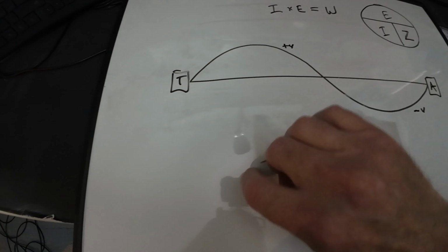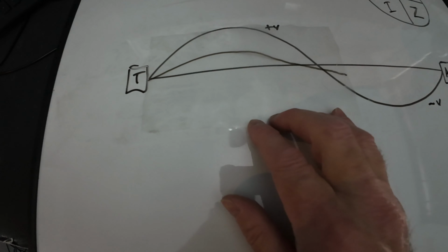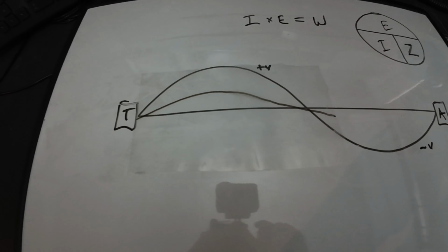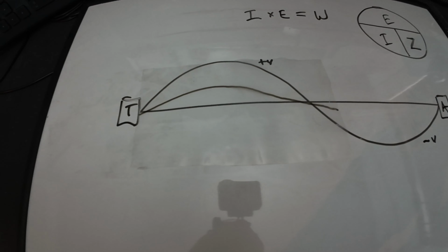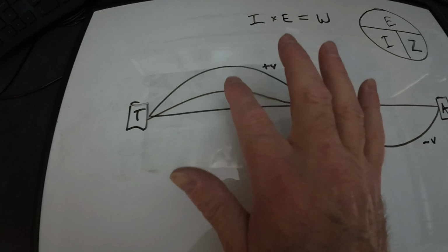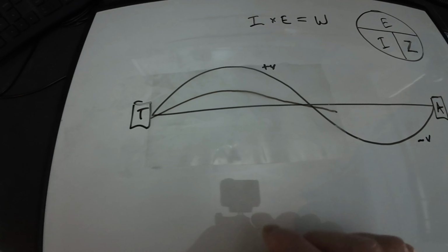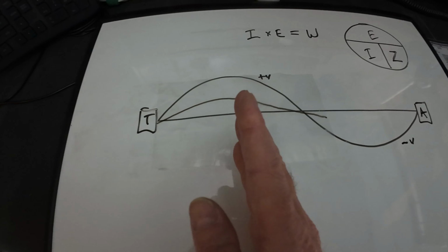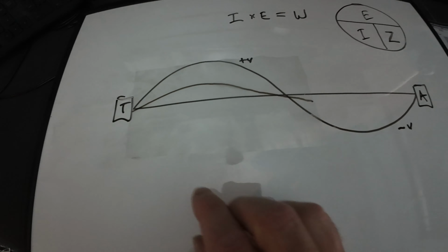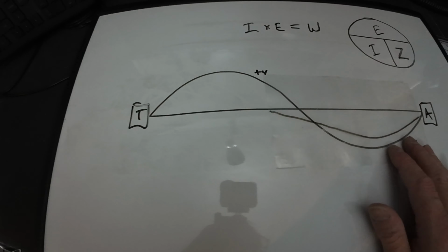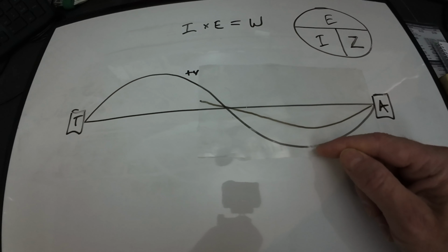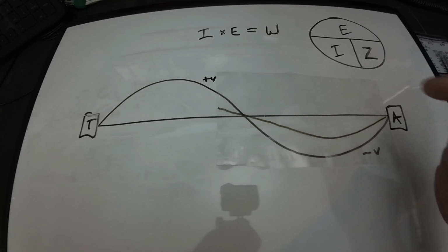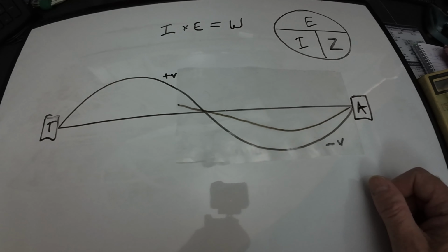And that's because everything is in phase. Because if the voltage and current waveforms are consistently in phase, the relationship between the voltage and current is going to give us a Z that relatively stays the same along that transmission line. No matter where we are on it, it should stay the same. The relationship between voltage and current gives us a Z that's going to be around our target of 50 ohms.